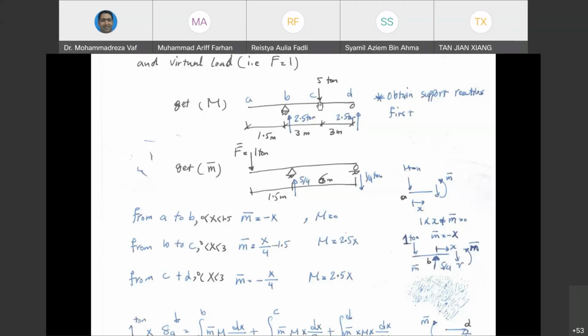So if you want to calculate the bending moment, all from left to right, the upper and lower should be the same. Or if suddenly you feel that from the right side the calculation is easier, you can move your origin to the right side and say that 2.5 multiplied by this x is giving me the bending moment, and you put it here. From down here also 1/4 multiplied by this x gives me the bending moment, and you write it down here. The most important thing is that you cover all spans and you get the bending moment for all three spans separately. The origin of x can vary, meaning, for example, for the second part, you could say that I want to do the calculation from the right side. If you do that for the upper structure, for the second structure down here you should also do the same.